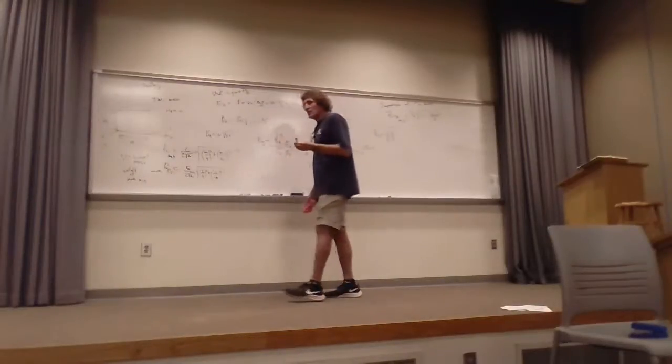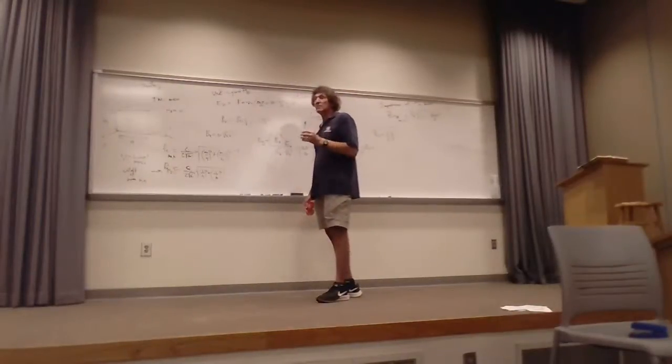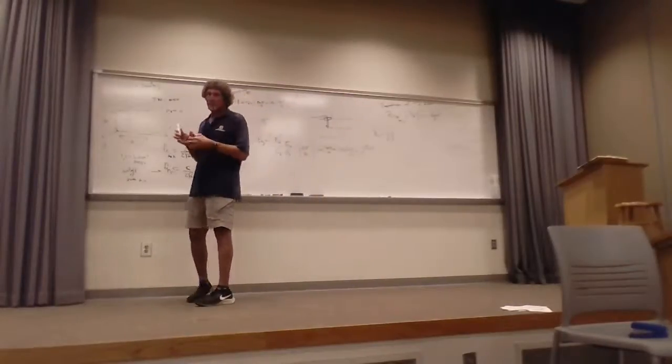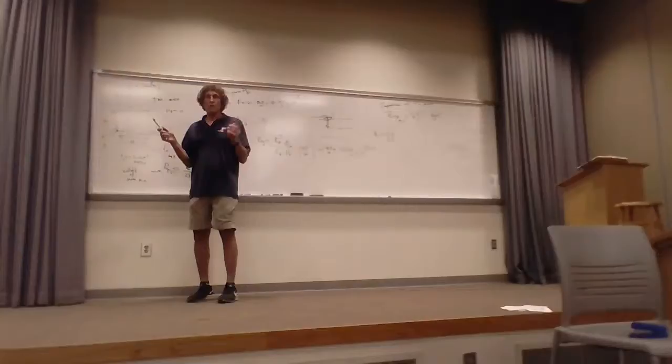So almost always, everything we use the waveguide for is going to be in the 1-0 mode, and it'll be TE. So I'm just telling you that right now. TM is not that important. You need to know this because there are certain applications where you want to develop both a 1-1 and a 1-0 mode, and here's why.